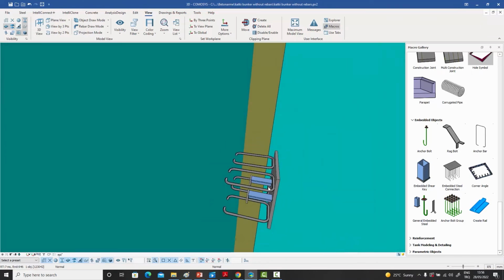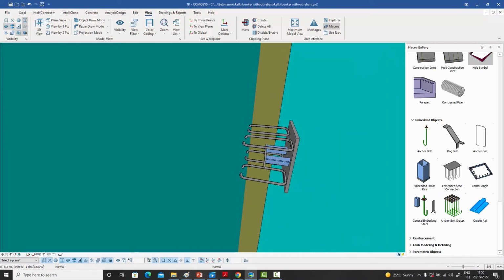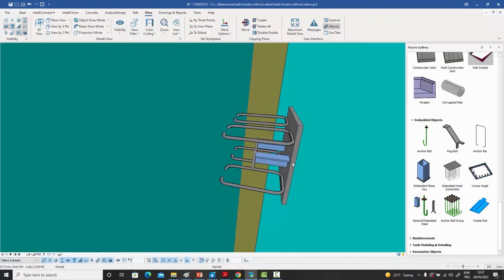So these options are very powerful. You can save hundreds of different types away, or however many you use in your company. And once you have them saved away, which is very easy, not time consuming at all, you can very quickly go through. All you need to do is just select points, like I just showed you. You put your work plane on the wall, or on the slab, or on the inclined wall, or wherever it is that you're working, and you just basically point and shoot. And it's as simple as that.